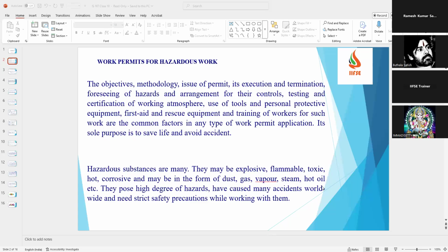When you say that, the requester will raise the permit. The reviewer and the approver, do they visit the site, or is it a desktop approval? No. Actually, we have to ensure the site conditions, whether it is favorable or not. If any additional precautions are to be taken, any suggestions or requirements, those are also to be communicated, and then only will it be reviewed, accepted, and approved.